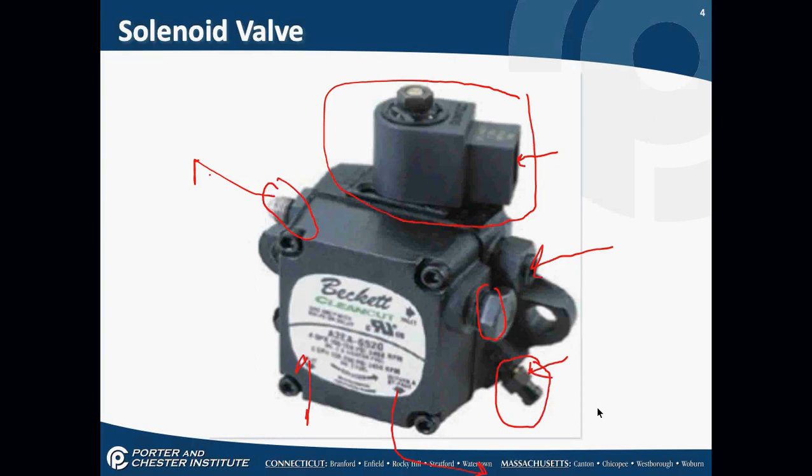Relief valve? That's my bleed valve. This little nut, this is a flat-sided 3/8 inch nut that actually has a fitting on it that I could put a small hose on. You know those clear little small hoses. I could slip that on the end of it, and I can open that up, and it will bleed the oil out of the pump. The minute I open this, I have no more oil coming to the nozzle.